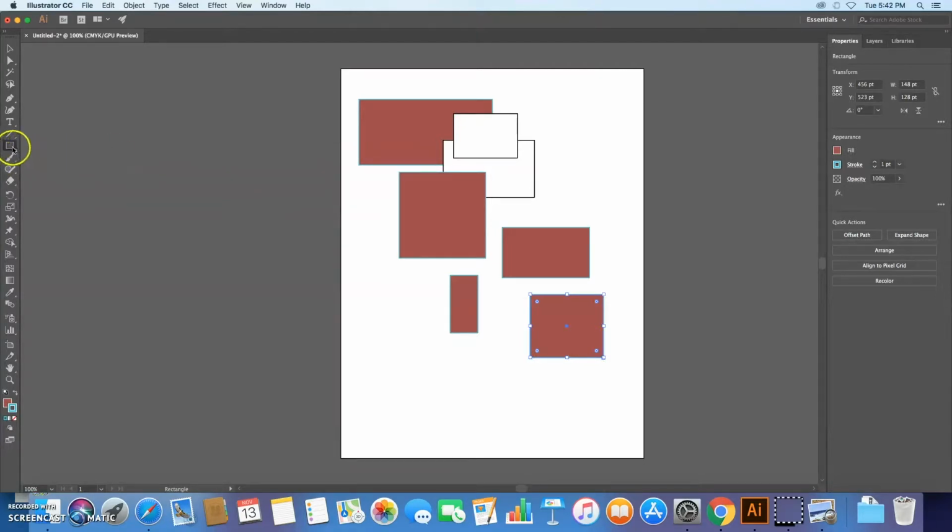And there's a bunch of shape tools here in this group that all work pretty similarly. So if you see this little white arrow in the corner of the tool, that means this tool is in a group of similar tools. So I can right click or click and hold on this to pull out that sort of drawer of tools in my toolbox, and I could switch to a different tool. The ellipse tool, for instance, works almost exactly the same as the rectangle tool. It just draws ellipses instead of rectangles, or if you add Shift, then it will draw circles instead of squares. The only difference here is with the ellipse tool, you can also use the command key, if you want to draw from a point actually on the circle instead of drawing from a point on a sort of imaginary square surrounding it. But I usually don't bother with that.